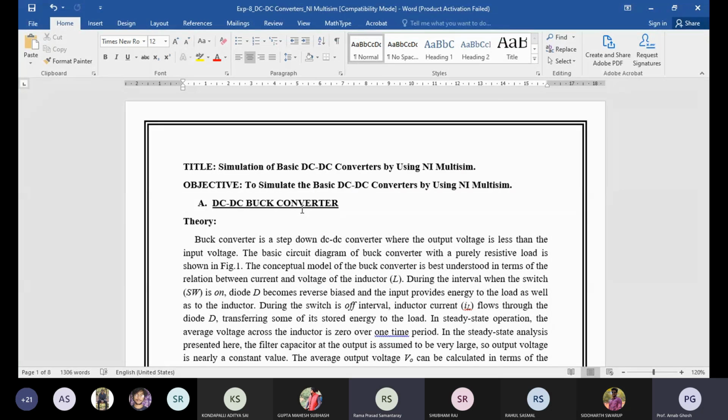Basically, that is the transformerized DC-DC converter. You know the buck converter is non-isolated; if you go for the isolated one, the name changes to forward converter. Normally, an isolated converter is designed for what? Basically, the isolation of your input side from your output side, as well as for multiple outputs.